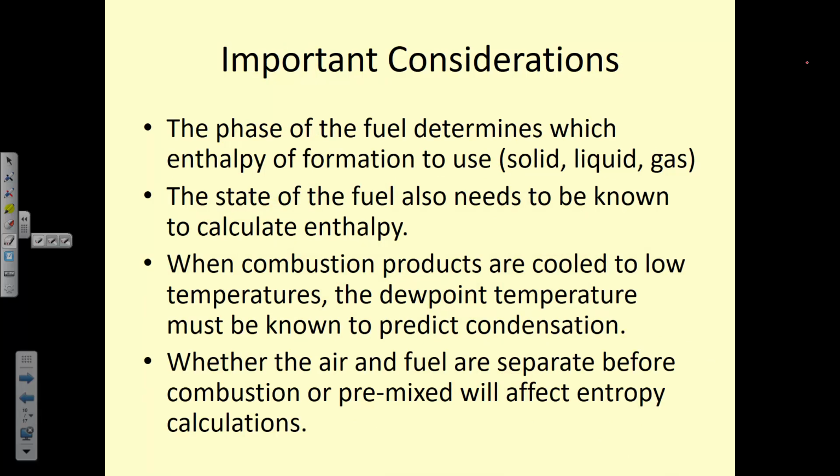Okay. So it's important to consider a couple of things. One is that the phase that your fuel is in determines your enthalpy of formation. So if you're dealing with a liquid fuel or a solid fuel or a gaseous fuel, you would use a different enthalpy of formation term than if it was in a different state. And those are tabulated here. This list is by no means comprehensive of every fuel that exists, but there's one that's out there similar to this one.